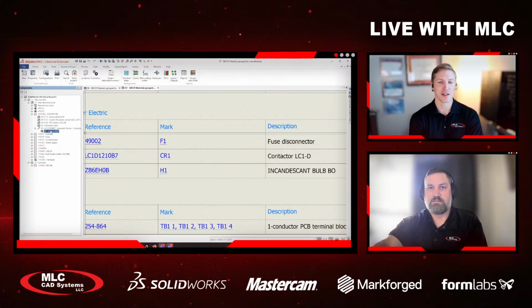That's pretty sweet. I mean, that's sometimes how I use configurations in SolidWorks, where I have one part file, maybe four configurations of it, like extended, shortened, simplified for a big assembly. You know, it's represented different, but it's the same thing in the BOM. It's one part. Yeah, absolutely.